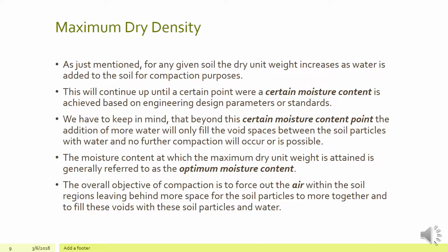The overall objective of compaction, again, is to force out the air within the soil regions, leaving behind more space for the soil particles to move together and to fill these voids with these soil particles and water.